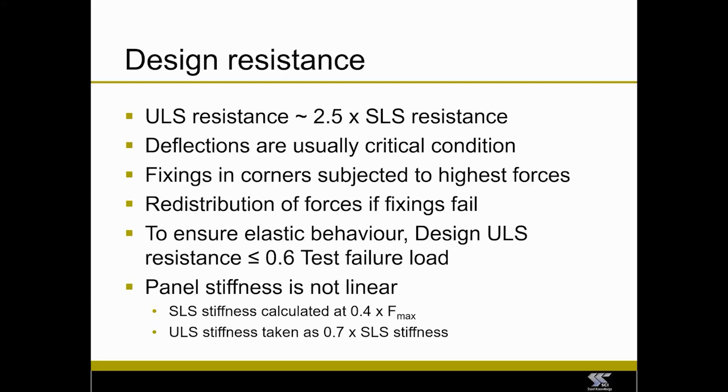And that leads us to the next point, that the ultimate limit state resistance of these boarded panels is limited to a maximum of 60% of the test failure load, to make sure that we are within the elastic range. But because it's the stiffness or the deflection case that is the critical case, it's really the calculation of the stiffness that is the most important thing from these tests.